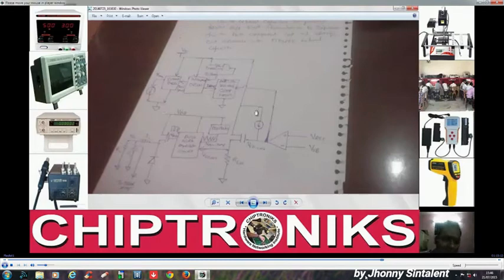We'll not go into details of this circuit, but we have to understand that nowadays internal soft start is there, and no external capacitor is used. And what is soft start? We have already understood what soft start is. Soft start is that when output voltage is 0, we need to generate pulses slowly, right? We need to generate those pulses slowly.